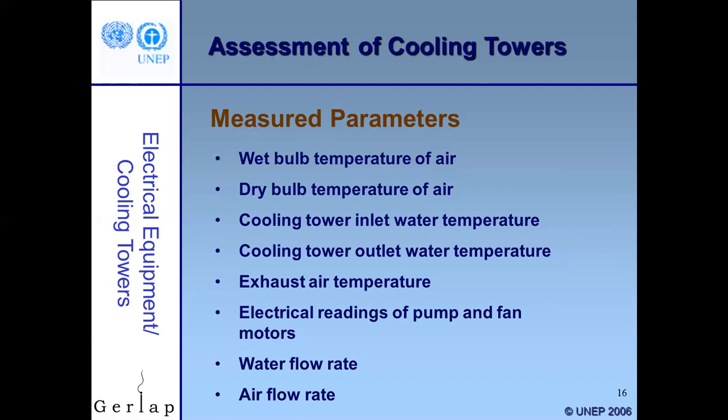The dry bulb temperature of the air, the cooling tower inlet water temperature. Is this an HVAC application? Is this an industrial application? Typically in HVAC, like I've said, we see 95 into the tower and 85 out of the tower. Some designs these days are trying to minimize the condenser water flow to save energy, so they may upsize the tower and have a lower flow with a higher temperature. You can transfer the same heat with less flow if you let it get warmer, but of course then you have to make sure that the chiller manufacturer is good with that as well.